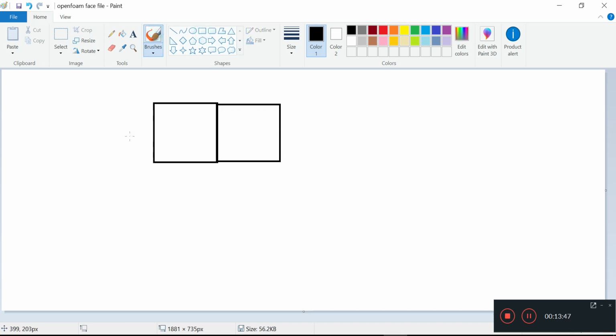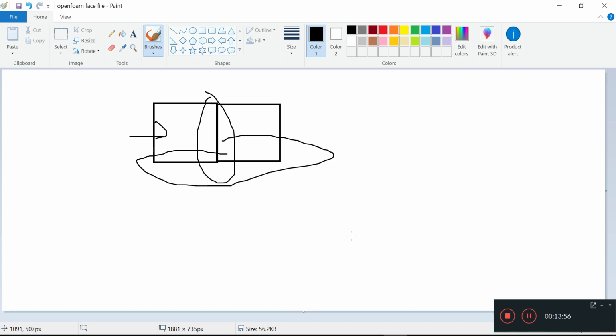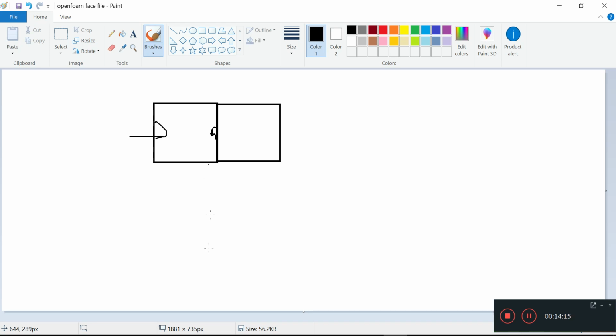Okay. But yeah, now that you're forcing the flow in, especially with a smaller mesh size at the center and here, OpenFOAM's gonna scratch its head. It's like, what's going on? We can't adjust the outflow, so to speak. I mean, the initial guess of velocity here is maybe too far from the actual velocity that you're trying to guess. Yeah, so that kind of gets an error.